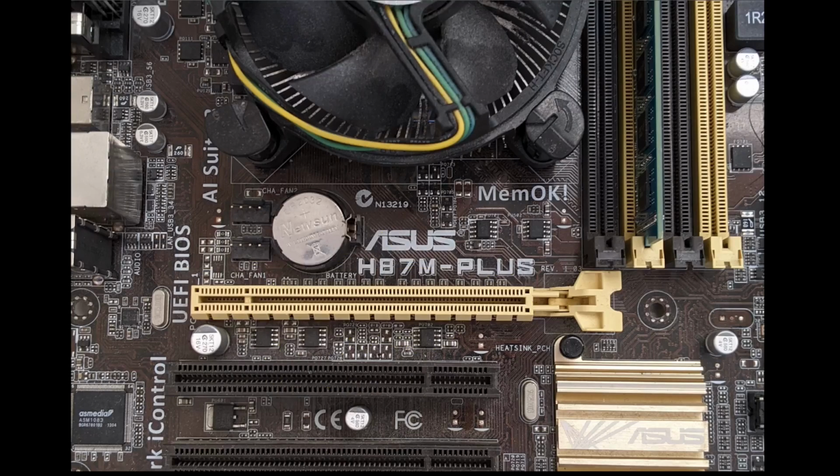If an X16 slot, like we show here, is only able to power X16 peripherals, the compatibility for devices will be a huge problem. Obviously, PCIe supports link negotiation between the host and the device to automatically select a link speed using the maximum amount of lanes supported by both sides. For example, a network card with only 4 lanes would be able to negotiate an X4 speed inserted into the X16 slot here. There are some caveats in this process.